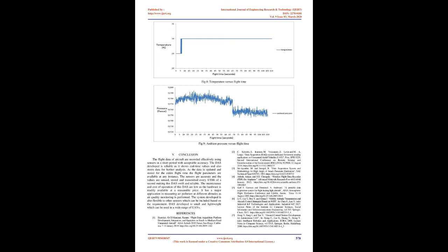4. Results with graphs. The sensors continuously sense the data and store it temporarily in Arduino. This temporarily stored data is transmitted through the onboard XBee router and is received by the ground station XBee coordinator. The signal is processed and displayed on the LabVIEW GUI with real-time graphs. Also, the sensed data are stored in a micro SD card using the SD card module in .csv format.